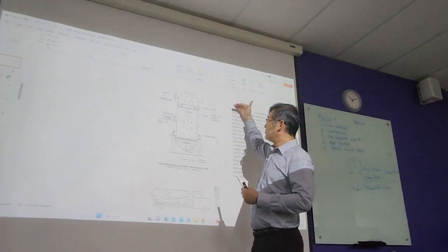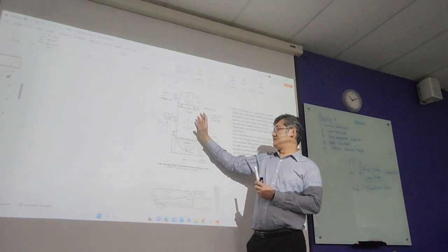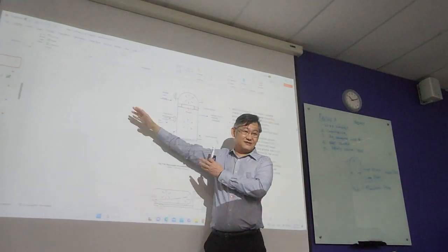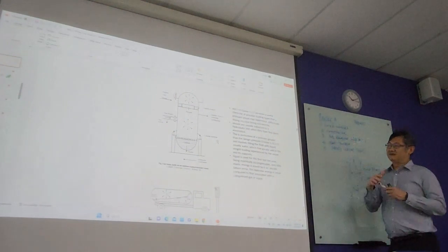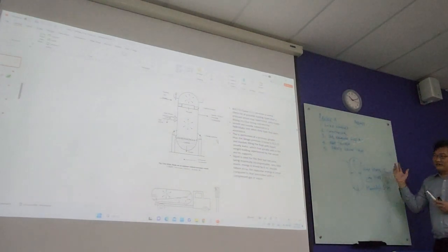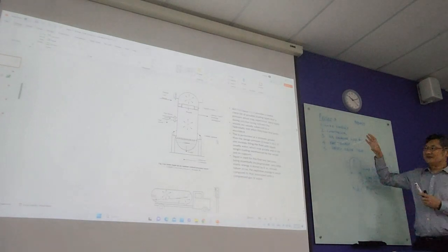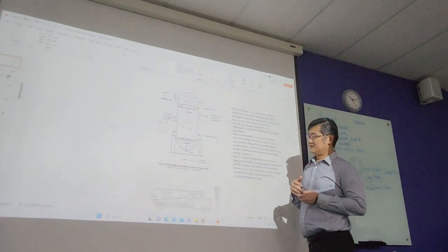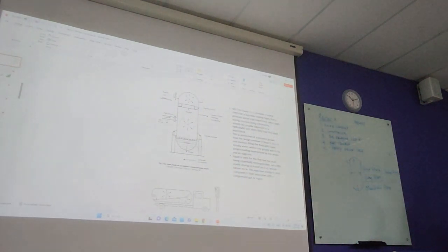When the wind blows in different directions, because this is vertically situated, you have a torque value, because it will bend the cylinder a certain way. If the wind is strong enough, it will actually bend the cylinder. All this we will simplify as a membrane stress on the surface. Later when you read through your course notes, you will realize they actually mention this.